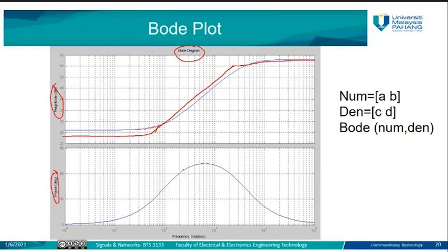And the same is the case for the phase here. As you can see, the phase starts from 0 and increases a little bit, but until some point it will be considered as 0. Then it will go to 90 or 45 or 60, whatever. Then it will go straight. I mean, all the representation will be without curve, without round. It will be a direct representation with lines. It will be a linear representation of the frequency response.